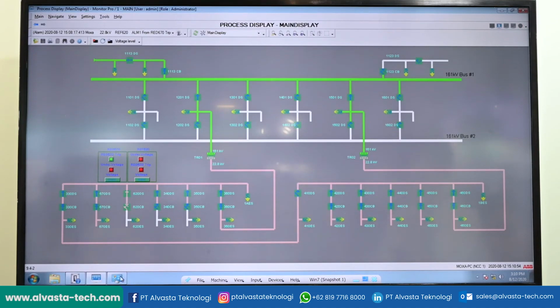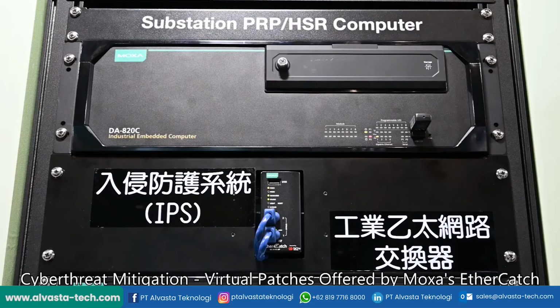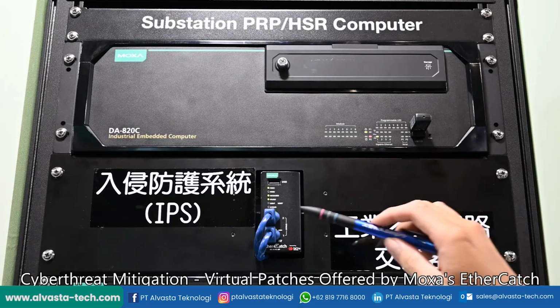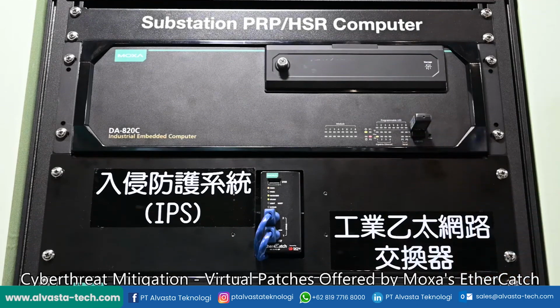In this example, we have an unpatched Windows 7 computer, so I was able to use a publicly available exploit for the RDP protocol and easily cause the whole system to halt. To overcome these challenges, we can put in additional protection like an IPS in front of SCADA computers. It can provide a function called virtual patch.